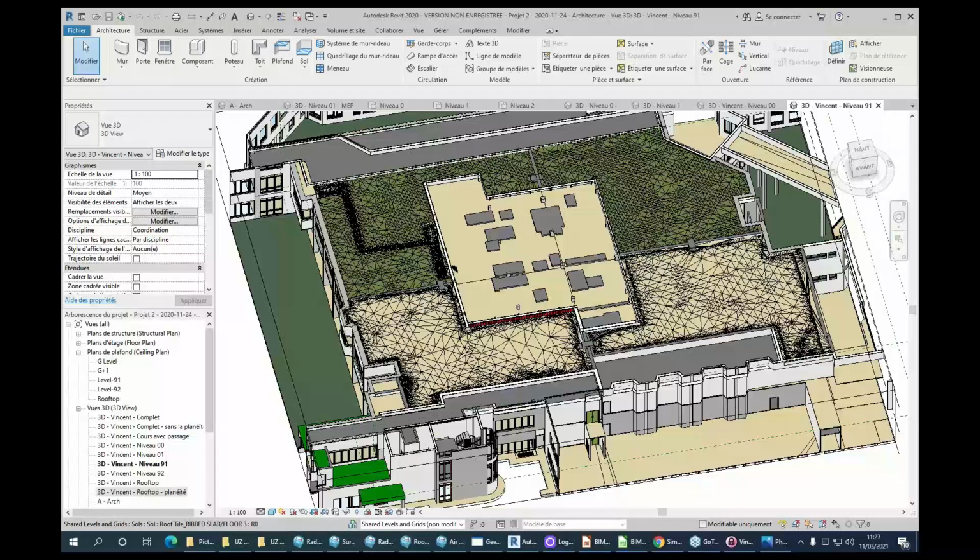Yeah, and if I may add, it also depends on the grid interval that you choose when you do the scanning. And there are techniques like using targets, using topographic references, etc. There are techniques if you need a really good match, but normally, what Vincent said is the normal result that you could expect to get.